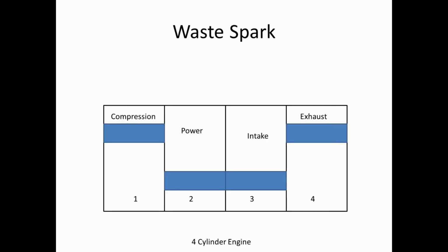So we're going back to the crudely drawn diagram again. What I have is basically a cutaway side view of a four-cylinder engine. The little blue things we're going to assume are the pistons. So we have cylinders 1, 2, 3, and 4. Now the way most four cylinders work, as far as every four-cylinder that I've ever seen, the two end cylinders are in sync with each other and the two center cylinders are in sync with each other.